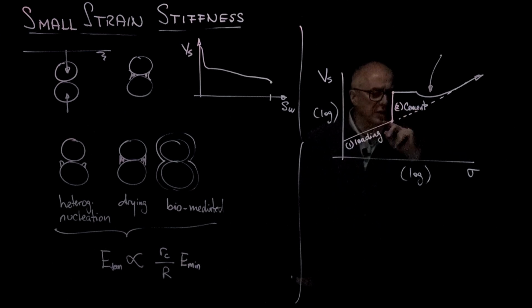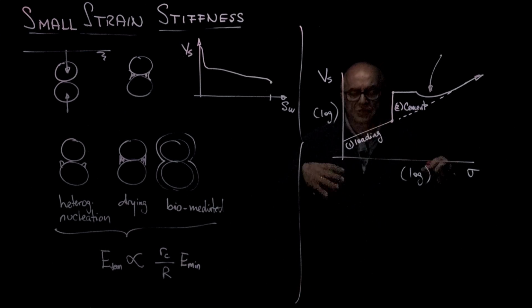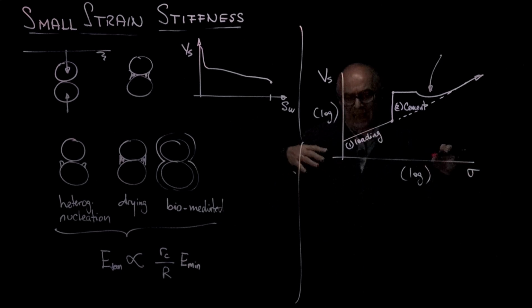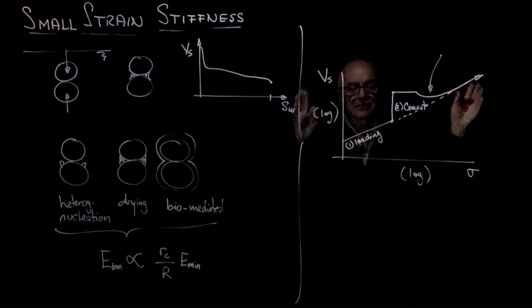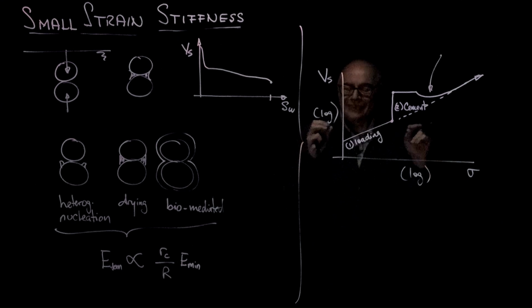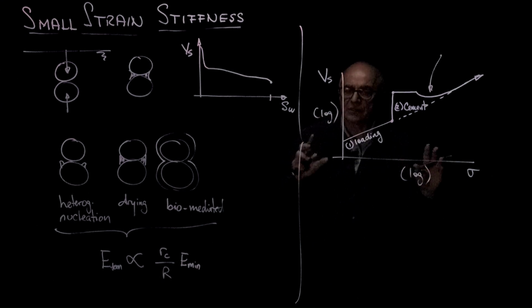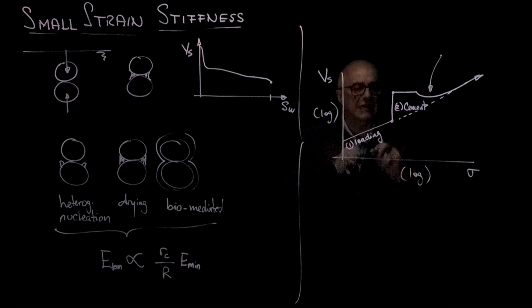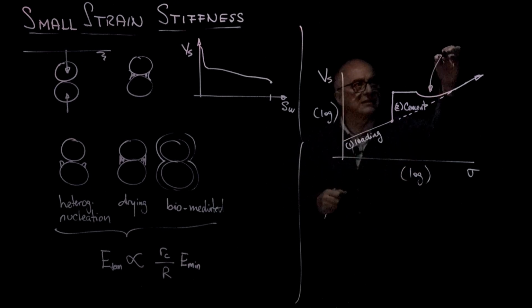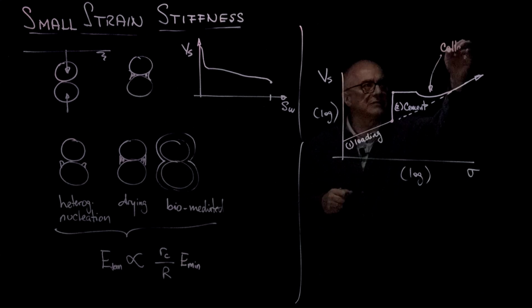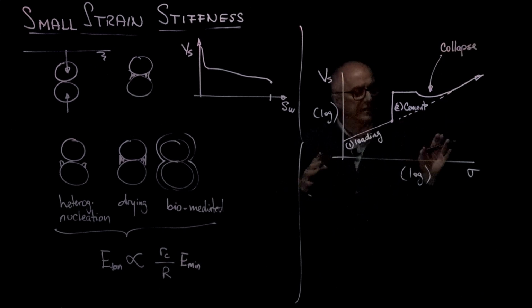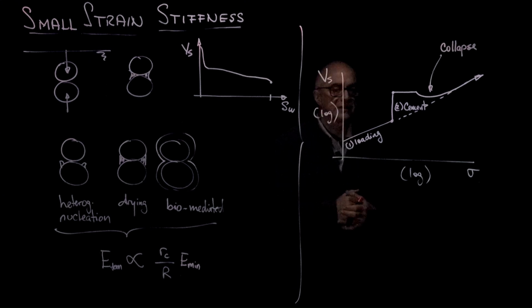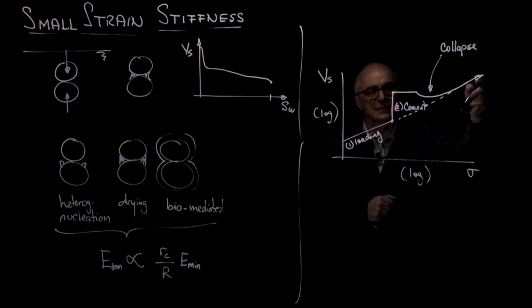This is a very critical situation where the cementation breaks. And this situation may lead, for example, to the collapse of layers in fly ash deposits or mine tailing deposits, and may lead to something like the Brumadinho failure. That very light cementation that we completely destroy when we sample the specimen may have a very important effect. So this is some structural collapse during loading, and will be primarily the situation where we have materials that have developed some diagenetic cementation. And then it goes back to the Hertzian behavior.